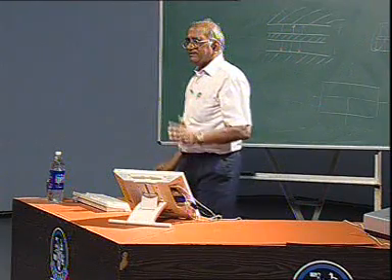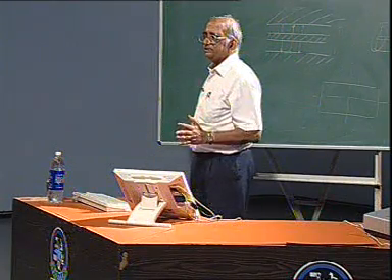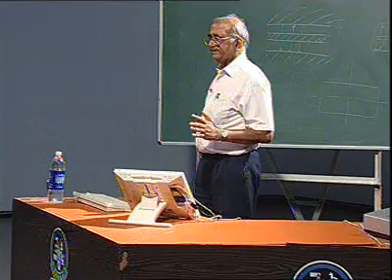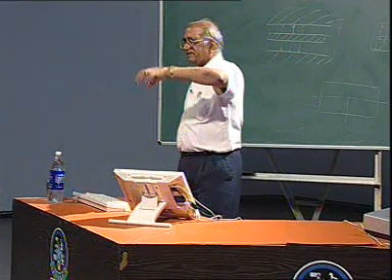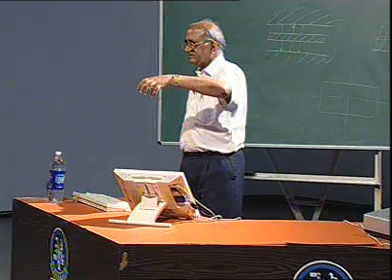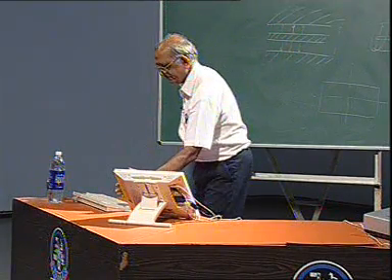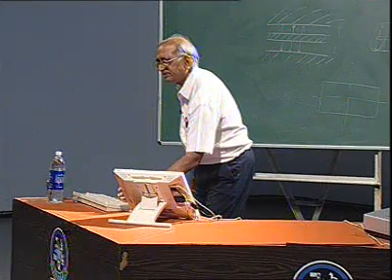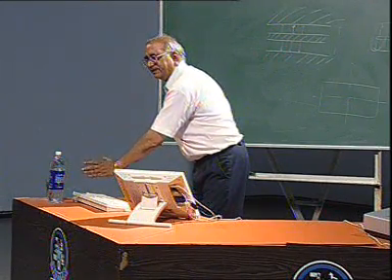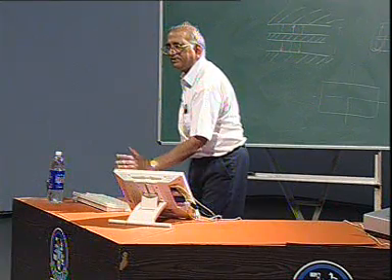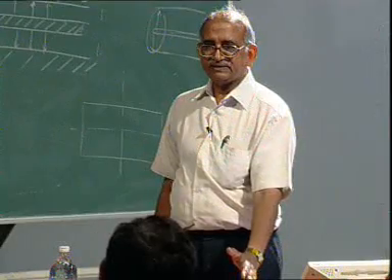And the receive antenna, if you are using, let us say, a horn antenna, can be rotated, and that will determine the polarization. Say you have one particular orientation of the horn antenna, it will go like this, then you rotate it through 90 degrees, again take the radiation pattern, and you will get a different component of polarization.